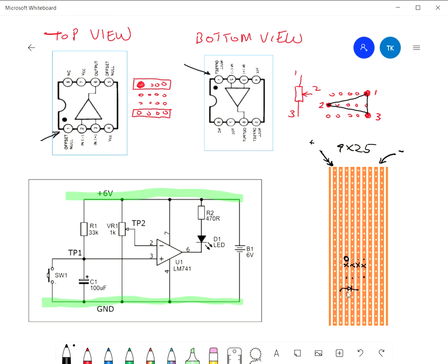Okay, I'll just write D1 there so we know that's the LED, and we're going to connect it to R2, which is the resistor, to the positive rail. So this is my positive rail, and I want to use R2 to connect to my LED there. So I will put my R2, I'll leave a blank row just for space again. This is my R2, not much space, but you know what it means, and I'll connect it across there.